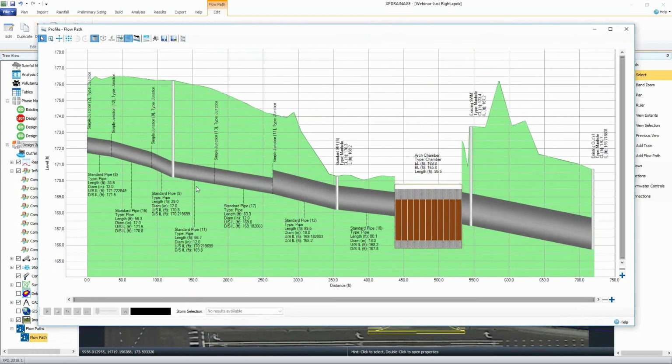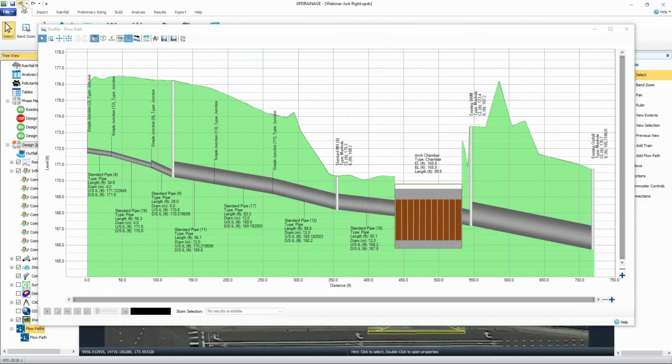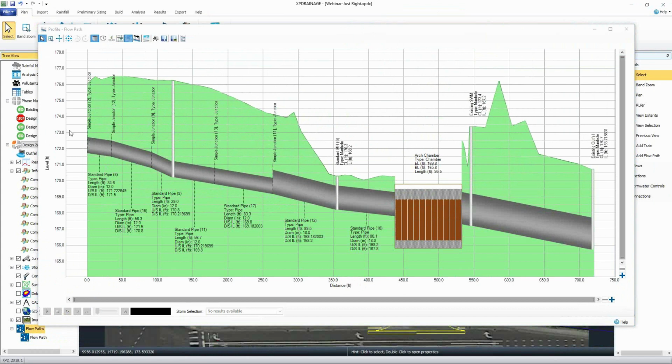Now, I assume everyone had perfectly memorized what the pipe network looked like before, but I can actually just jump back in time, hit the back button. That's pretty useful, actually, to make a change. What was it before? So you can see a much smaller pipe network, okay? Probably a lot cheaper to put in the ground and to buy. Well, hey, based on our probably pretty conservative, rational inflows, we have to bump all of these sticks of pipe up. There you go. That's what a preliminary sizing would give us.